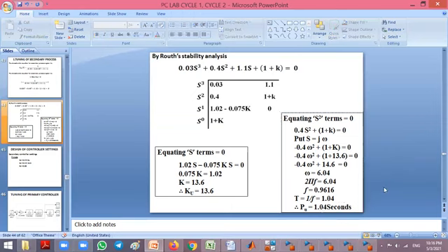So now you can decide what controller you can put for the secondary loop. You can go for P or PI, proportional mode of control action or PI mode of control action. Generally for the secondary loop, these two controllers are preferred, and in our process we are doing only P control. For implementing only P control, this term alone is enough, but to have knowledge about how to calculate Pu, I have derived it here. If you want to go for PI mode of control action, this procedure you have to use. So I have given this for your knowledge.